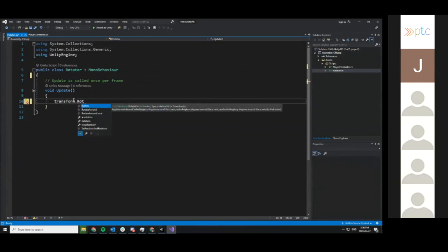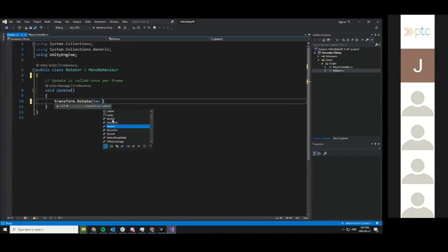One key thing in Unity is that we don't want to modify the transform's rotation. We want to rotate the transform. The reason is that the transform's rotation doesn't use a Vector3, so it ends up being not as intuitive as you think to modify the rotation. But transform does provide a Rotate function, so this is what we use. Here we can directly create a Vector3 and give it component values of 15, 30, 45. These are just random values that I picked that work well.